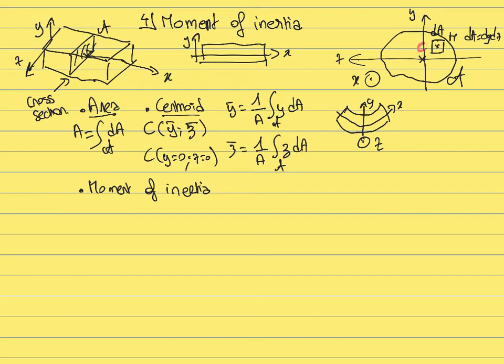You have the rotation of the beam. The beam used to be a straight line and now becomes a curve. It is becoming a curve because, for example, it is subjected to some moments along the axis z. So z gives you the direction along which the beam becomes bent. In this case, what will matter is the moment of inertia about z.